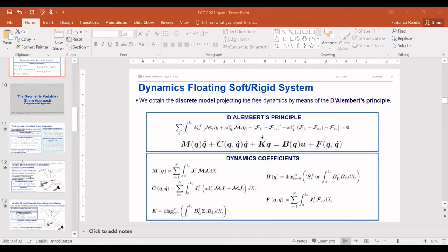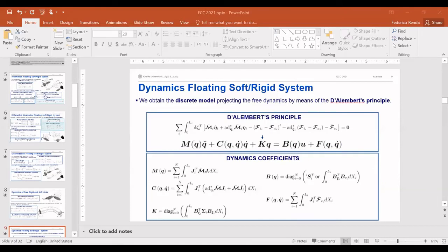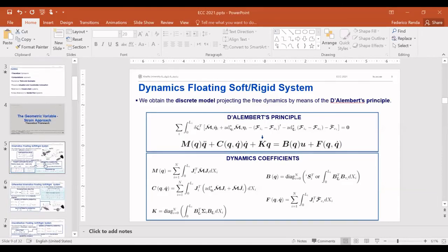I may have missed it because it was a lot of information, but don't you get problems, and maybe that'd be the reason of the spaghetti one you described, that you have inertia changes, right? If you have the more Hamiltonian approach, in which you basically use momentum rather than acceleration, then you consider the mass together, and then you can model it more naturally, if you wish. Because taking the time derivative of the element in the algebra is a discussable thing in a general context, because if the sections are not constant inertia, you get into problems. Could you comment on that?